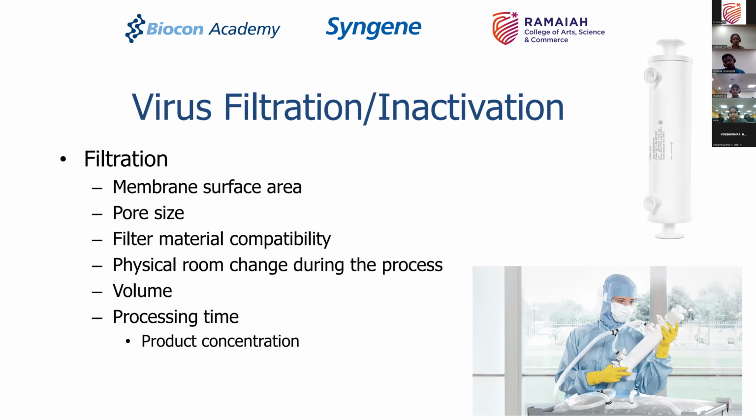Virus filtration and inactivation. Inactivation is generally achieved by changing the pH of the solution, and then you need to filter it out through a filter which looks like this. So it's a dead end filter, or just a single filter cartridge through which you send it. So the liquid is sent out and the clear liquid is collected. The virus is retained onto the filter and the clear liquid is collected out. So there, what is the membrane surface area which you need based on the volume that you are processing? What is the processing time? What is the load of the viral inactivated virus that you are expecting here?